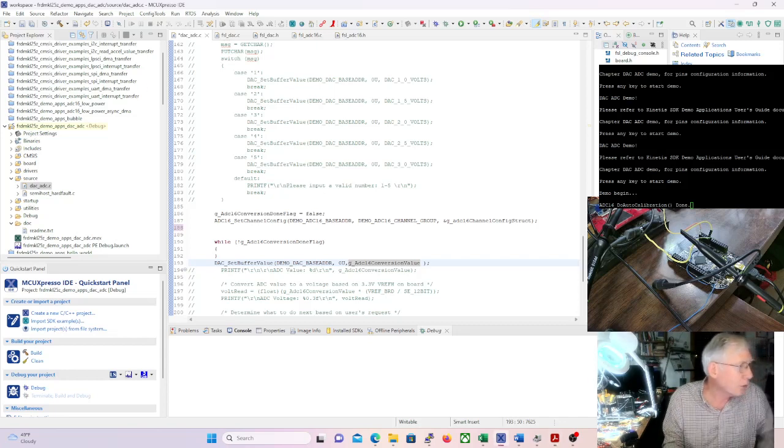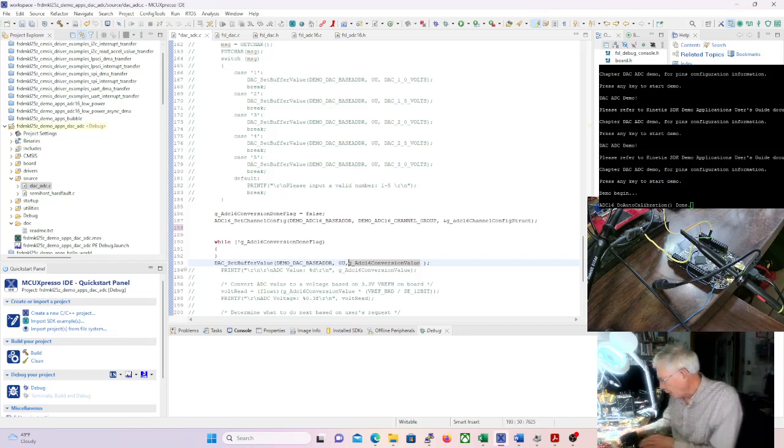All right. So you also like to have a terminal window. So here's my terminal window. I have a little picture. So here's my setup. These two pins right here, the inside row here, this is PTE 30 and this is PTE 20, and they're the extreme opposite ends of that inside row. And then we have to have a ground pin here, and we've got all of our grounds connected to this ground pin from the signal generator and also for the scope. Now my one scope probe is on what's coming out of the DAC, and somehow this ground came off. And then the other scope probe is on the signal from the signal generator.